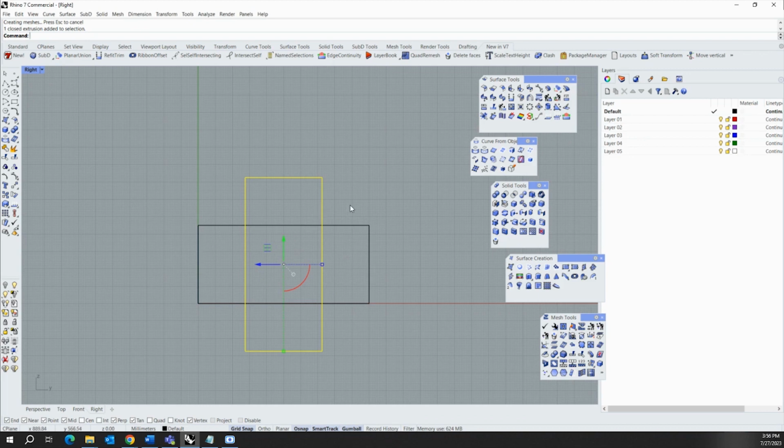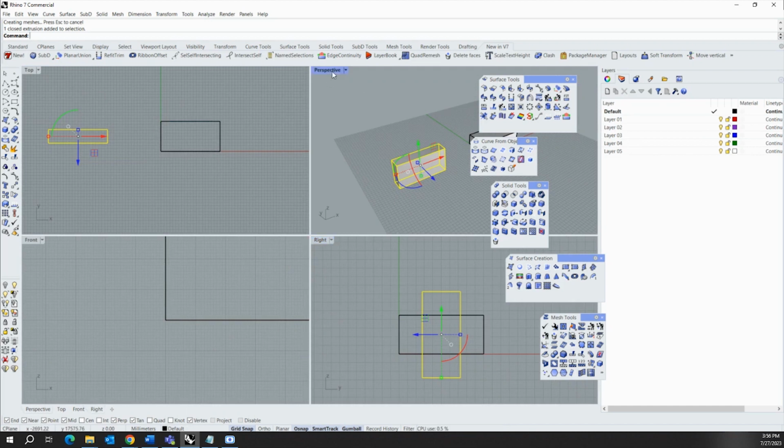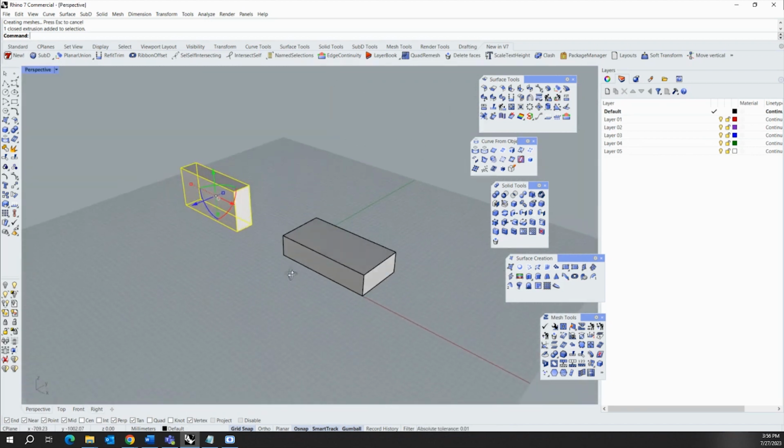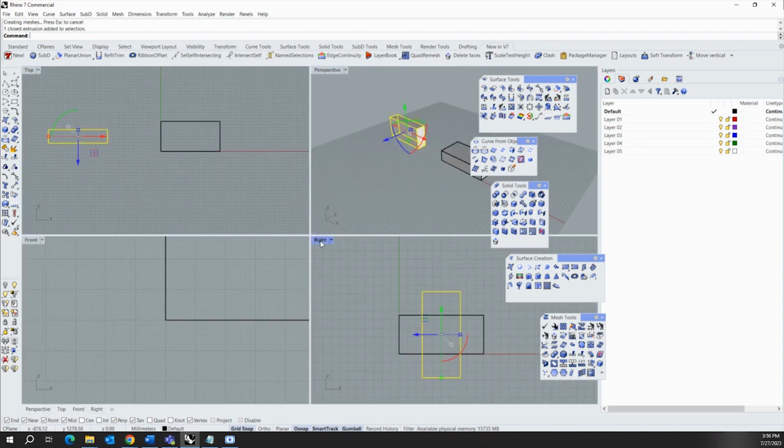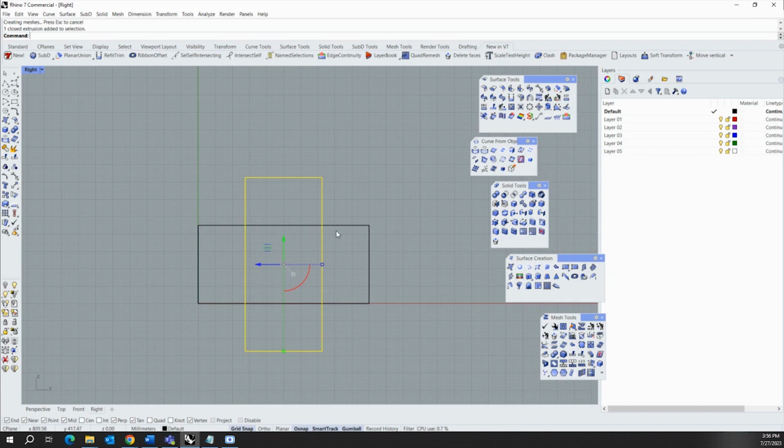Once after that, this is not the scale which we need, because it doesn't give you the exact similar output we have seen in that building image. So I'm going to use the scale option to scale it down by a few units. I'll be using Scale 1D, which scales only along one direction of this box. It doesn't scale it in 3D. I'll be scaling it down by 350